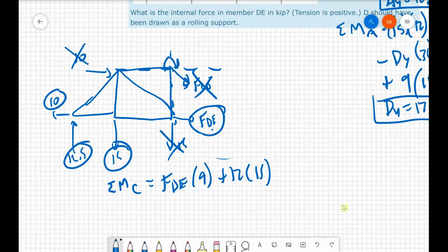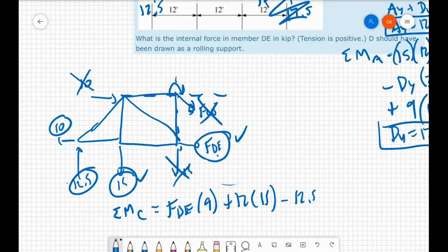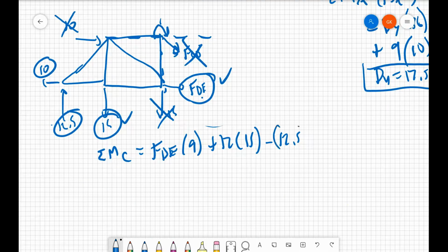And I have this guy right here. So let's, okay, a little check mark next to make sure I know I've done it. And I have this force, and that's going to be causing a clockwise turn, so it's negative. 3 times the distance of 24. And the final guy causing a clockwise turn, so minus 10 times 9.